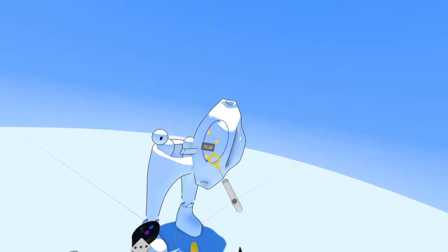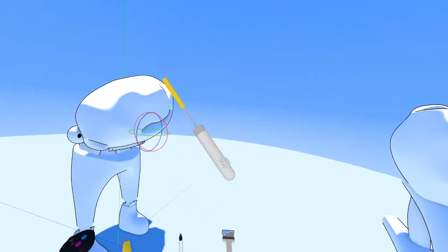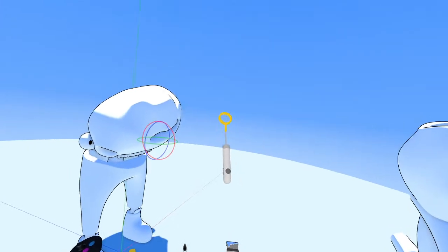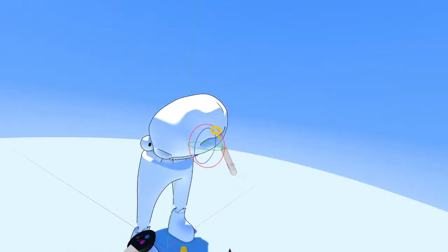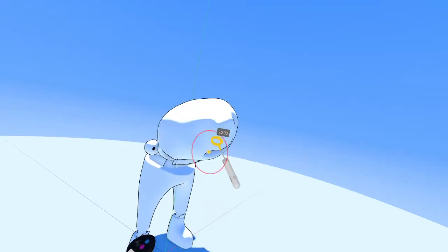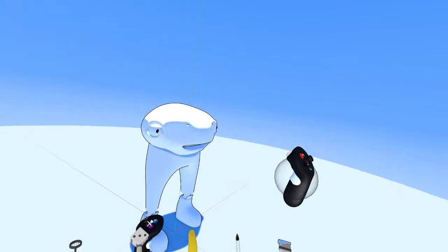It tells you how much you're revolving and how much you're moving, and then you'll see there's a little label there to snap, with a grid icon on top. If you press the color wheel menu, now you can snap along 15-degree increments. This is really a useful tool.